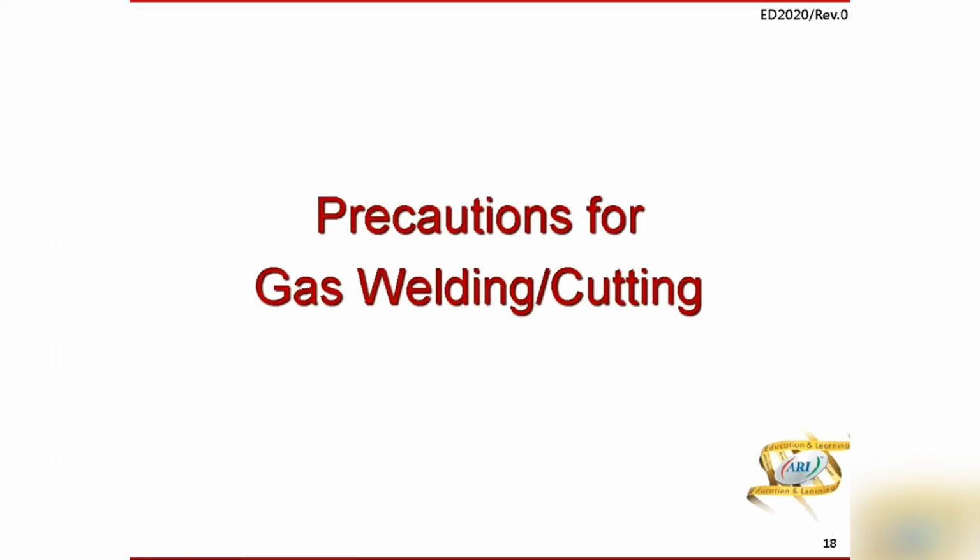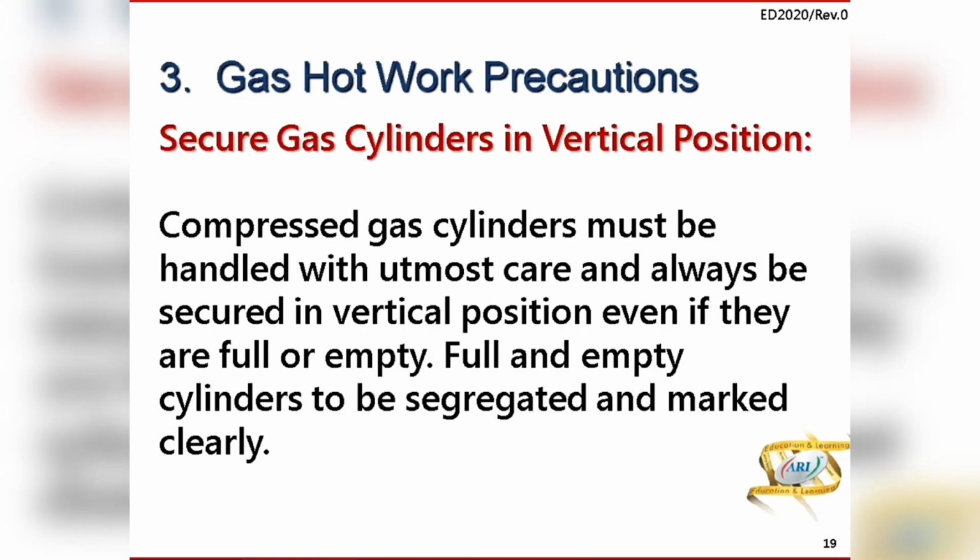Now, what are the precautions for gas welding and cutting? Secure your gas cylinder in a vertical position. It should be handled with utmost care and always be secured there in the vertical position, even if it is empty or full. Full and empty cylinders to be segregated and marked clearly.